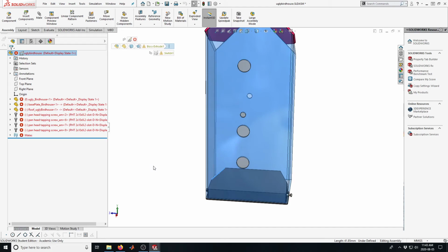So keep that in mind, that you can make lots of changes as long as the general topology, the features are all there. So you can change dimensions and spacings and that sort of thing quite easily. But if you make more fundamental changes, then there will be a rebuild problem. So you've got to really peel back to the beginning and figure out where those errors are and fix them.